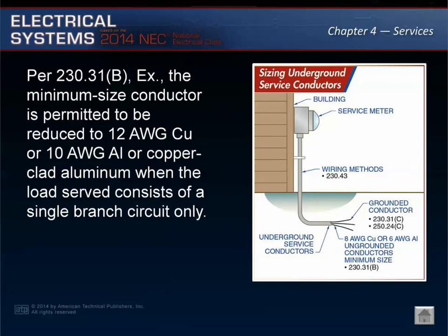Underground service conductors shall be sized to handle the calculated load per Article 230.31(A). The load shall be computed per Article 220. In addition, the underground service conductors shall have adequate mechanical strength for the application.